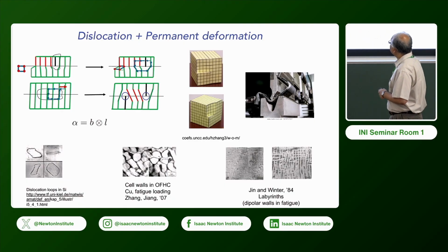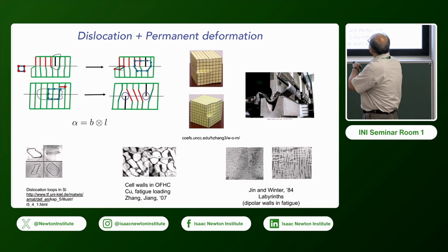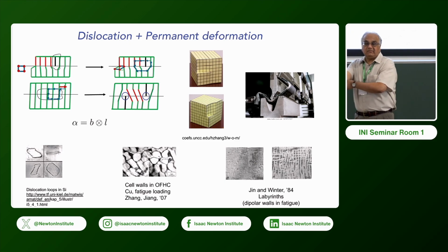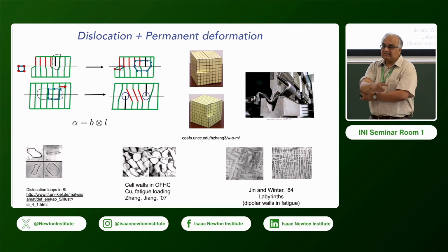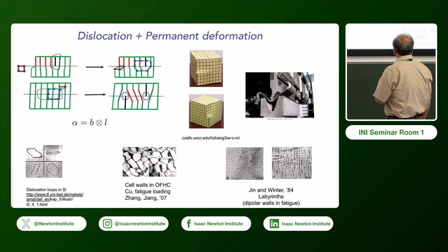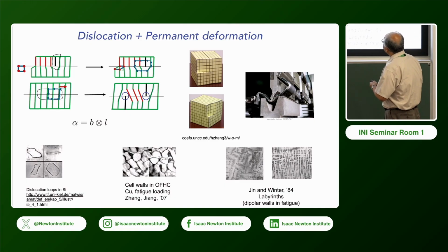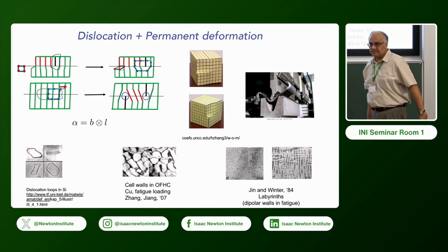The screw dislocation is interesting. If you think about this situation, you make a cut in the plane and then you shove in this part by 1 atomic distance. So that would be the Burgers vector. And for a screw dislocation, the Burgers vector is parallel to the line direction. And edge is when it's perpendicular. Of course, the line direction is changing, the Burgers vector remains fixed, so you can have mixed character of the dislocation too, as in this situation. See, here it's an edge, the line inside goes around, comes out here, it's a screw here.